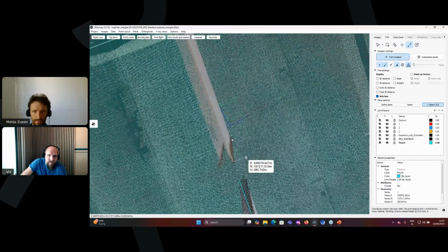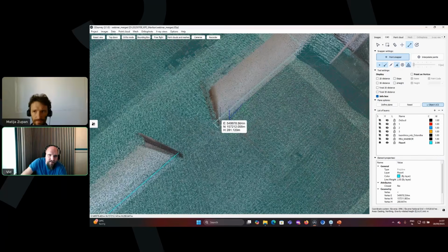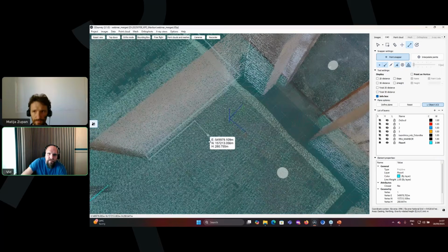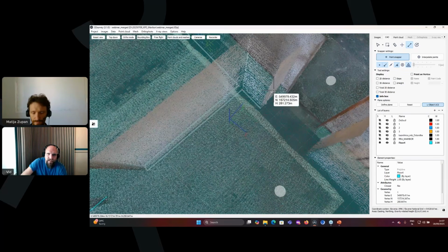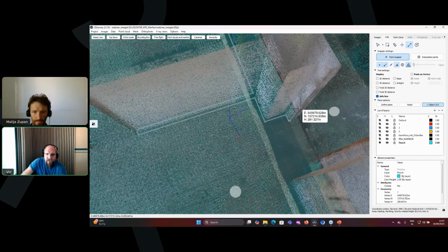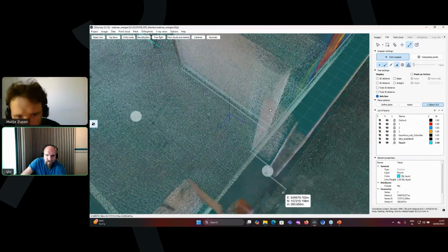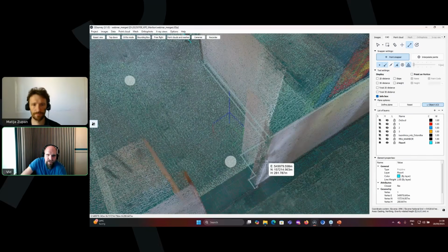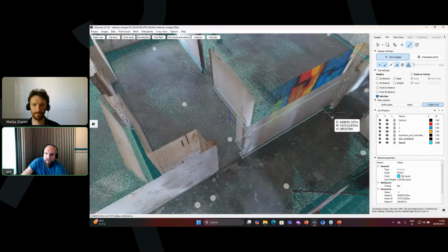And then in this direction, to extract the thickness of the wall, we can click on the other side of the wall section like that and continue back here and here. And you can already see like that, the digitization is a lot more user-friendly, because we don't need to take the points exactly on the edge. You can just click on the other side of the wall and snap to that. And we go back to here and then to here.